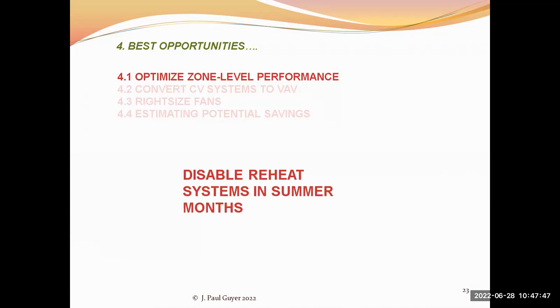If you do have a terminal reheat system in an older building, perhaps you can get away with disabling the reheat system completely in the summer months, and just providing cooling during the summer months. This has to be looked at by the mechanical engineer in evaluating what can be done.